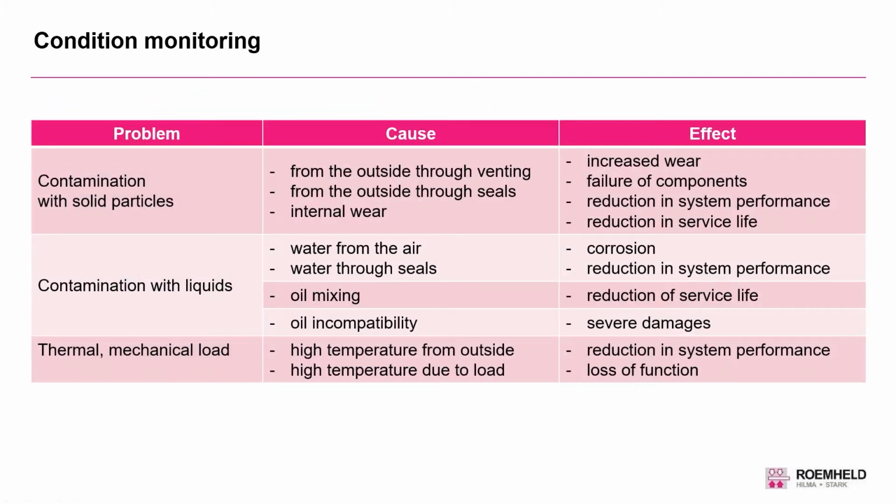A little bit about the problem cause and effect situation. I told you that we talk about contamination here. So we have solid particles. What is the cause? This is mostly coming from the outside through a venting system.